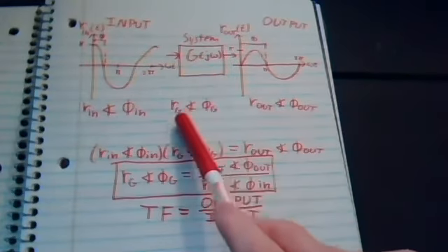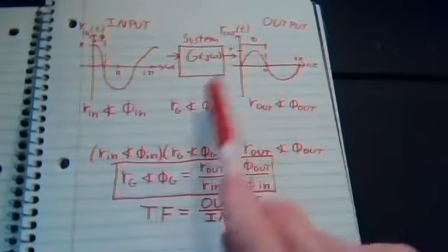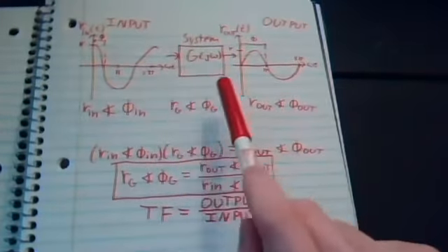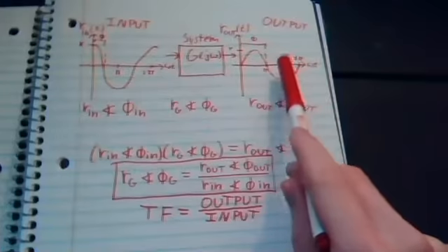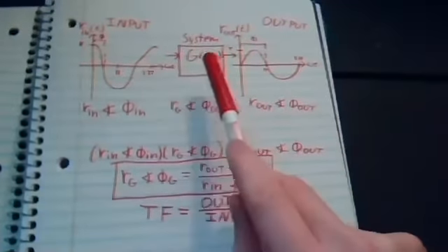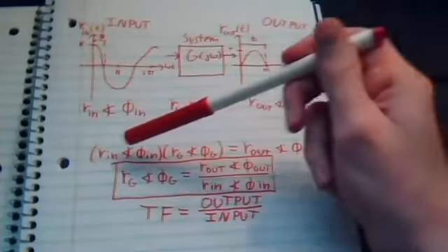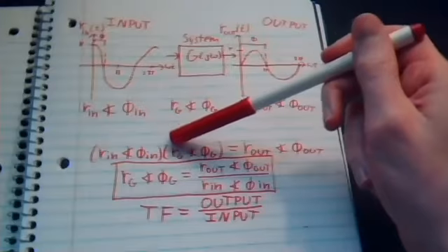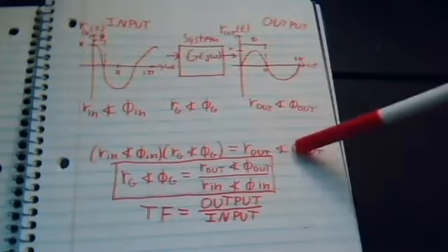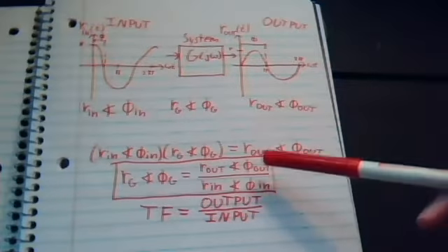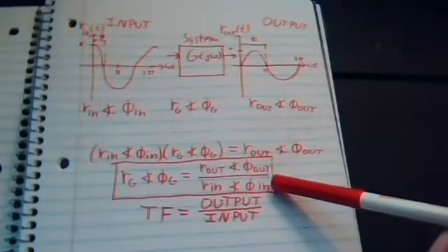And so we're after the system's response. And in order to do that, we can make this 3-picture diagram into an algebraic equation and then manipulate it a little bit. We can say that this output is really the result of multiplying these two things together. This input with the system gets us to this output here. And so we can say that our input magnitude and angle times the system magnitude and angle will be equivalent to the output. From here, it's simple algebra to just move the fraction over and get that the system is equal to the output over the input.